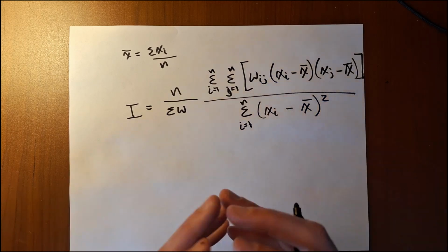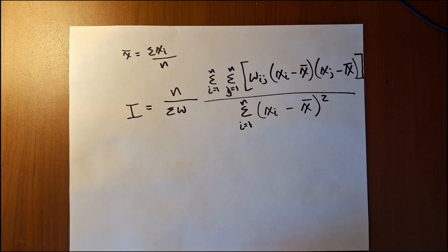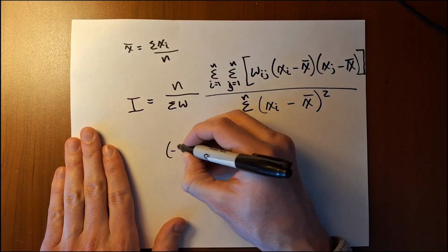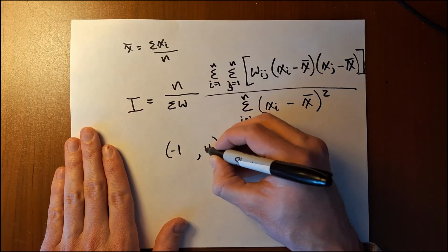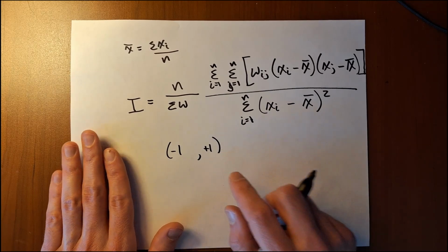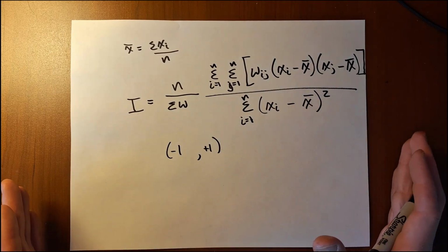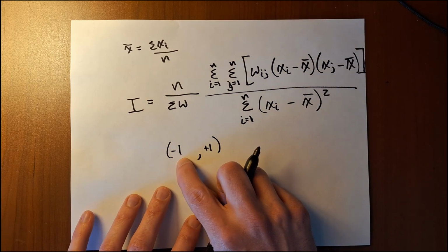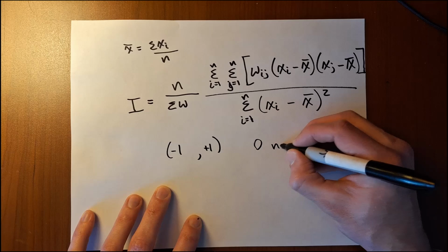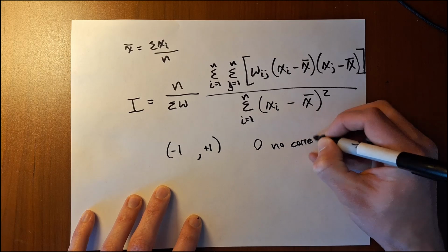So points closer together, we're checking for covariance and giving that covariance a much stronger weight, and then we're summing it all up, and we're going to get a value that goes from -1 to +1, where +1 means they're perfectly correlated in space and it's safe to do the spatial interpolation. -1 means they're perfectly negatively correlated. And values around 0 indicate no correlation.